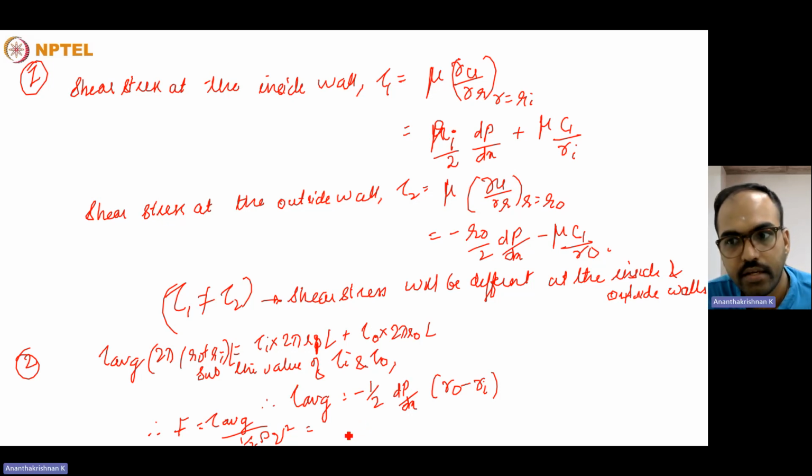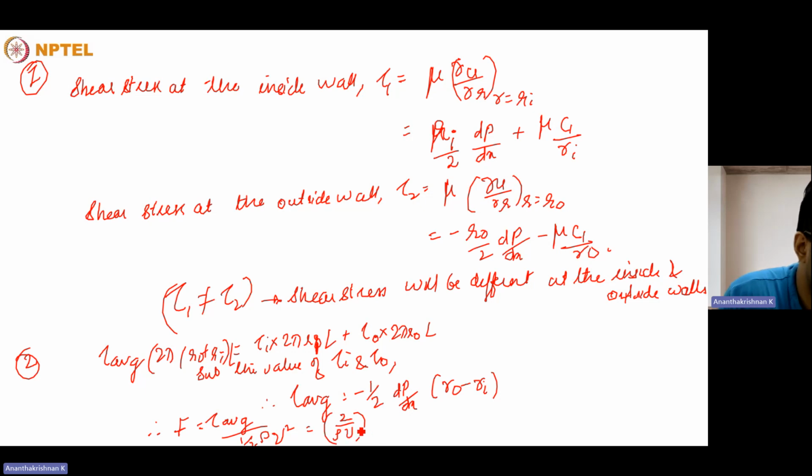But even then, for the velocity factor, you have to substitute the value of the mean velocity in this equation. We have obtained the value of the mean velocity, and we can make some simplification to this formula. You just separate the u into two terms: half rho u squared as half rho u times u, and then you can write this as tau average divided by u.